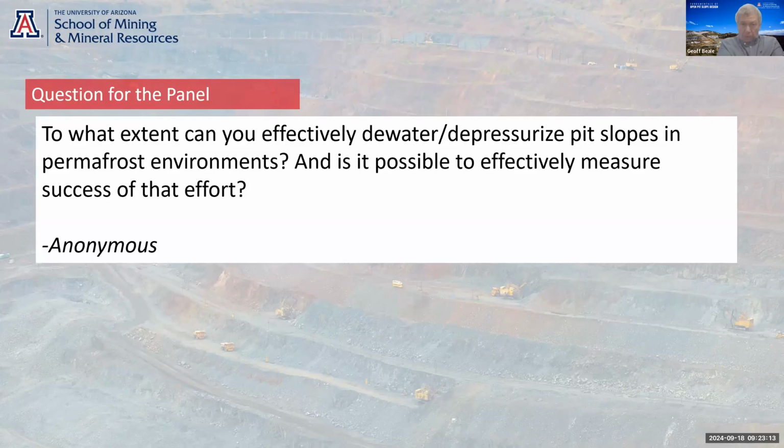Permafrost does not normally require depressurization, but when you go through the permafrost and get into the sub-permafrost environment, the risk, and many operations have had problems with this, is that the sub-permafrost groundwater is often under artesian pressure. It's confined by the permafrost. If you don't pre-depressurize it, you can get down with the pit, come out of the base of the permafrost and get quite high pressures, and that can create problems with mining and